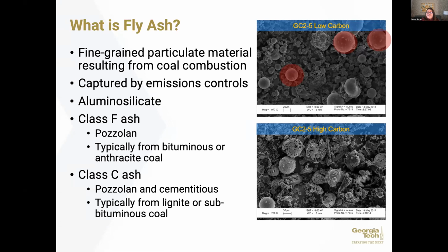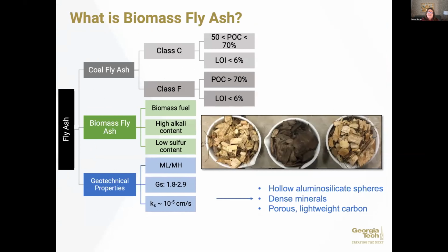There are other ashes though, which you see down here in the lower corner. And in this case, I'm going to highlight a couple of particles in these lower ashes that you'll see there. These are organic carbon particles that were not combusted within the fly ash, within the electricity generating process. These cause us some issues. And what you'll see in the US, when you have carbon content which is too high, in fact, those ashes must be disposed. They can't go into concrete, which is the most common use of fly ash.